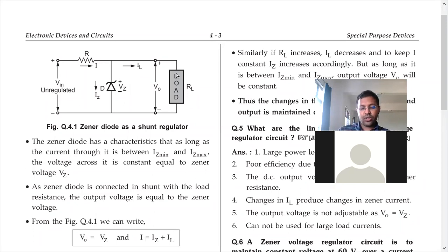Yesterday I gave you a motor. Suppose you connect a small 5 volts DC motor at the output, still the output should remain 5 volts. It should not change because of the load that we are connecting. Or suppose you connect a charger and want to use the output terminals to charge your mobile. When you connect your mobile phone, if this voltage is dropping, that is not a favorable situation. So we want the output voltage to be constant irrespective of changes in input voltage or changes in load.